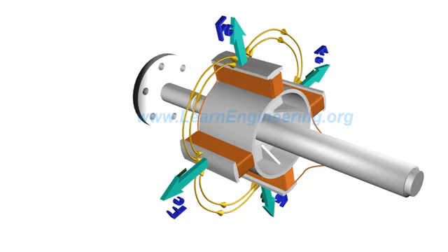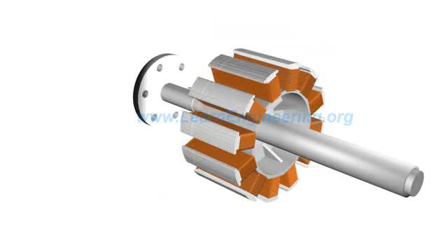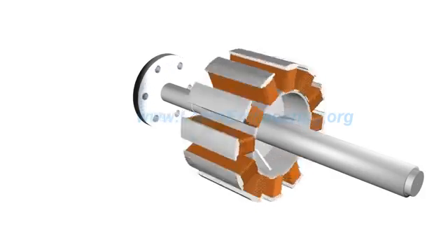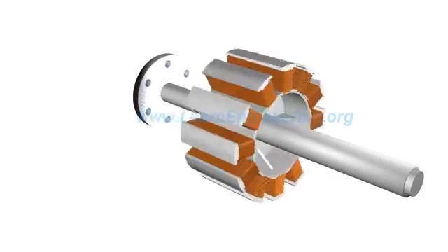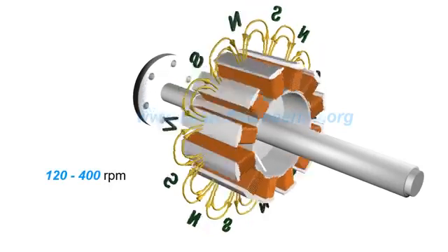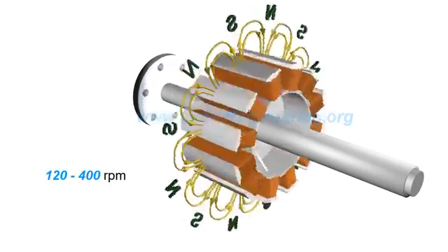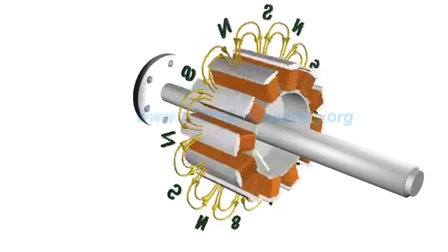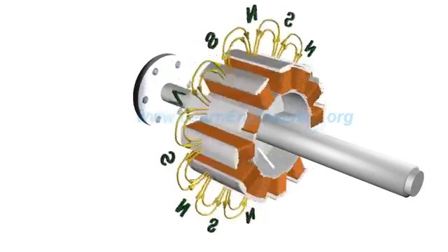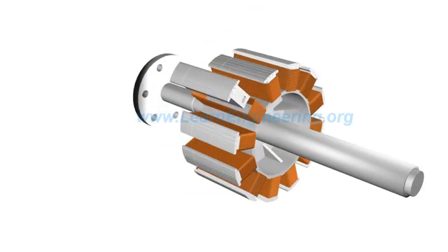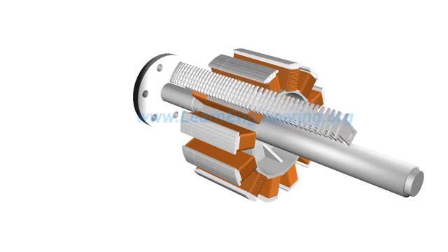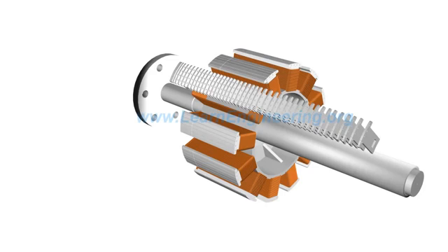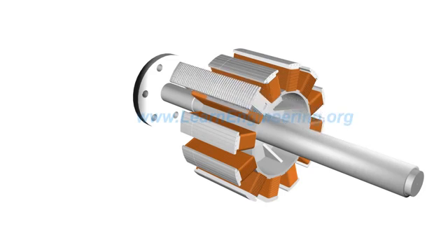So salient pole rotors generally have 10 to 20 poles, which demands lower RPM. Or, salient pole rotors are used when the prime mover rotates at relatively lower RPM. Pole core is used to effectively transfer magnetic flux, and is made with fairly thick steel lamina. Such insulated lamina reduces energy loss due to eddy current formation.